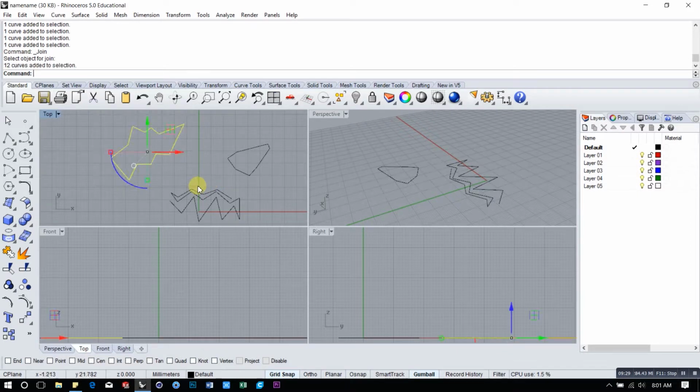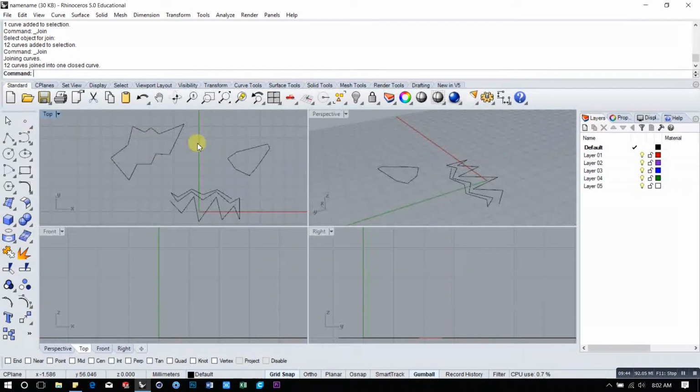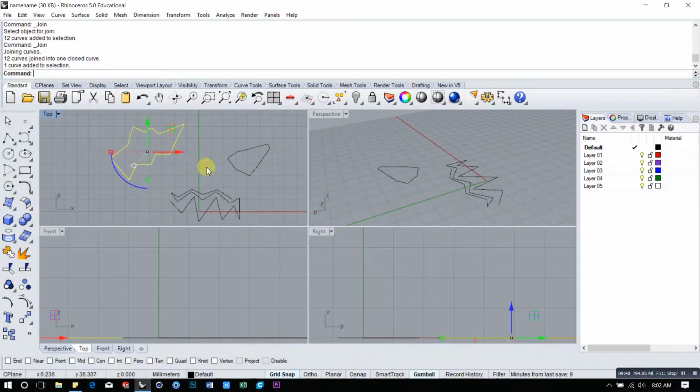Hold on. Escape to drop the tool. Select all the polylines in the mix. Hit the join key, and then it'll join them all together. Okay, so like I said, we're all learning here. Select the polylines you want to join first, and then hit the join button. There you go. If you turn join on first and try to select them after the fact, it doesn't work.